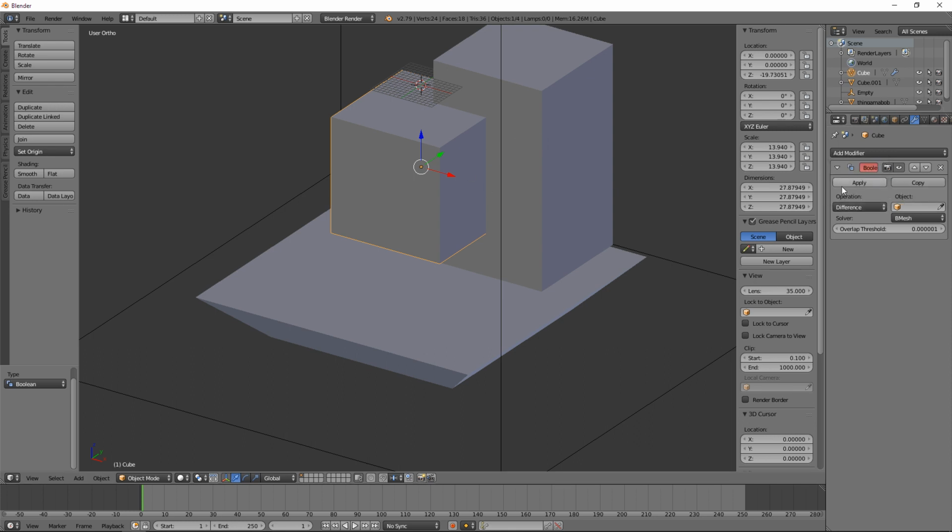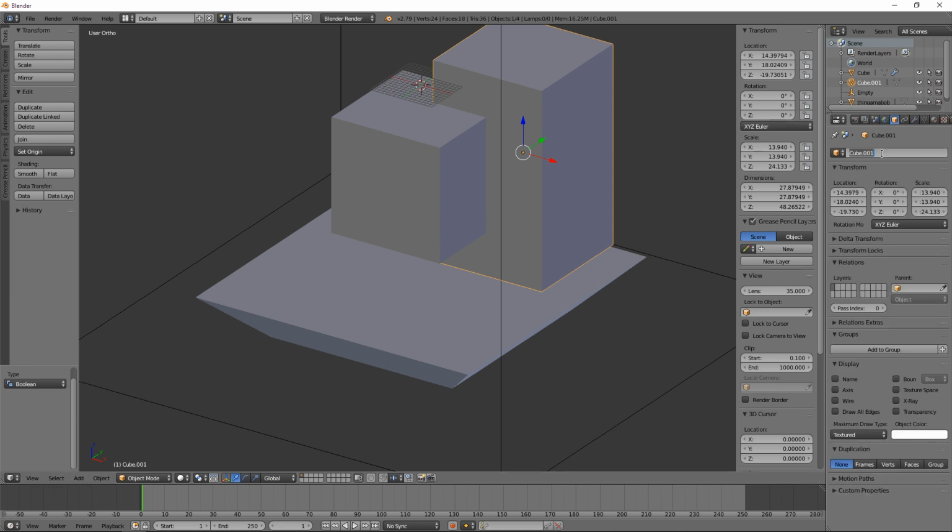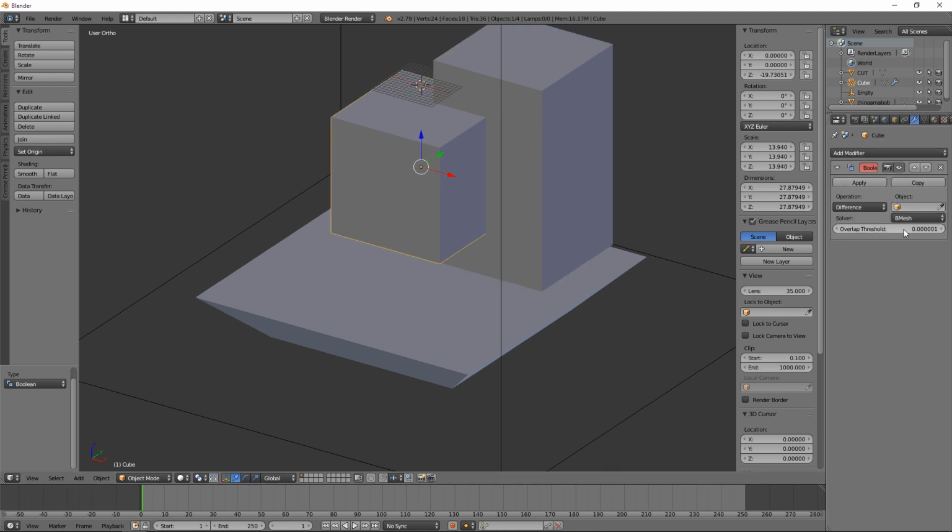We can either find that cube in a list because we will have named it like I just did. See, we could name it. And we'll just call this guy cut. That'll be the guy we're going to use to cut. So we can choose cut from the list. Or, this is a nice feature, eyedropper tool. And just eyedropper. Now you know that you've got the cut selected.